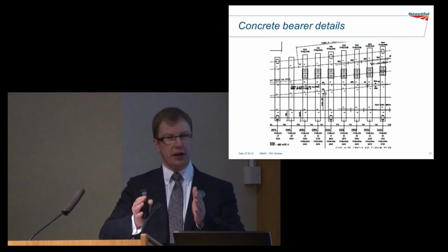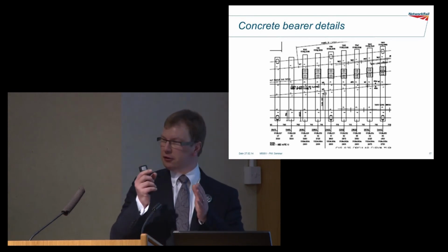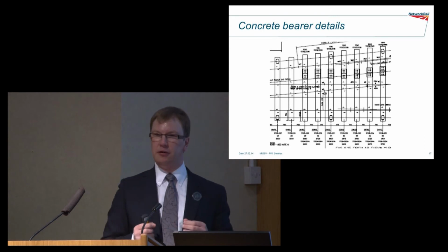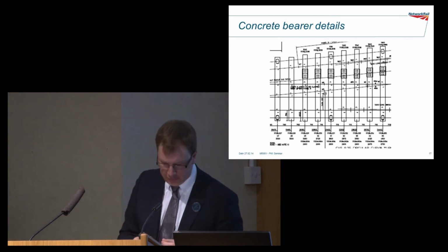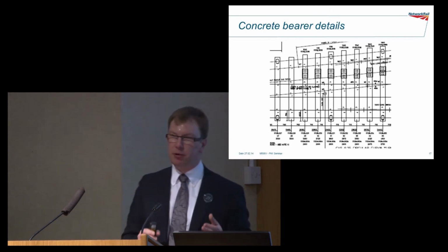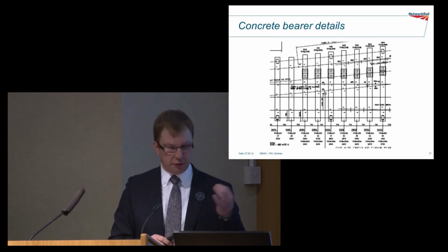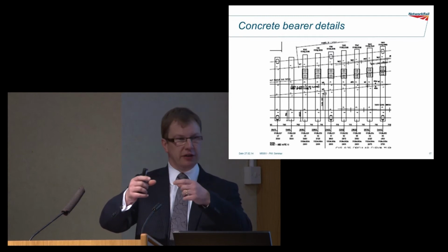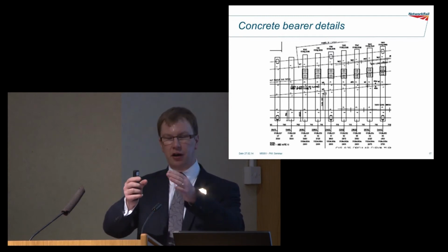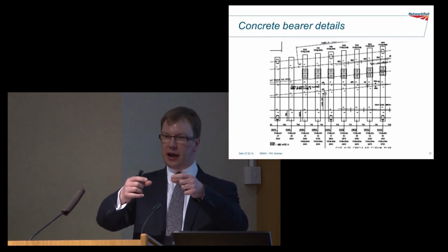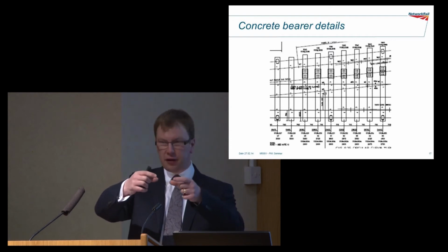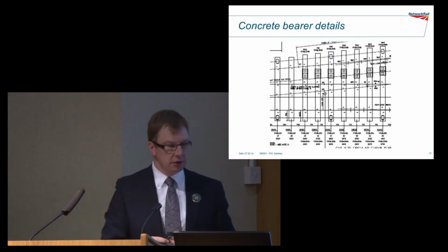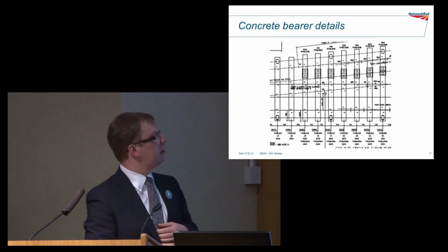As you start to rotate the housings round, you start to encroach and get closer and closer to the reinforcing bars. So we've had to develop a range of pads which I'll talk a bit more about in a moment, but effectively the stagger between the housings has to change. You can only rotate so far before you have to change the stagger between the housings, then you can only go so much further and you have to rotate it again. So I'll show you some pads in a moment.